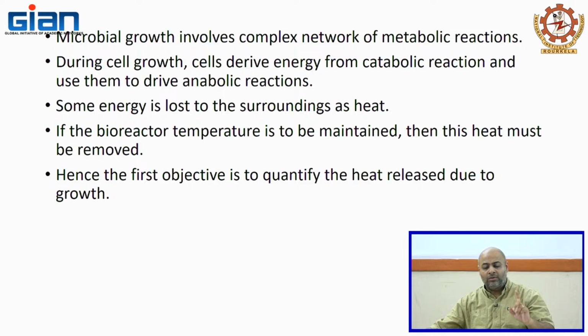So microbial growth involves a complex network of metabolic reactions. Now I am talking about the heat generation because of the microbes. During cell growth, cells derive energy from catabolic reactions and use it to drive anabolic reactions. Some energy is lost to the surroundings as heat. If the bioreactor temperature is to be maintained, then this heat must be removed. Hence, the first objective is to quantify the heat released due to the growth.